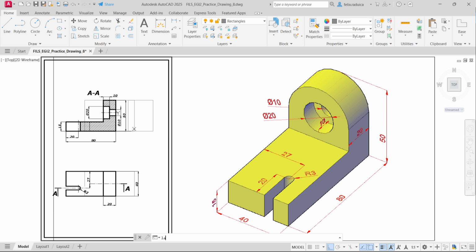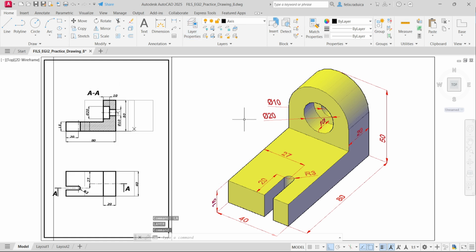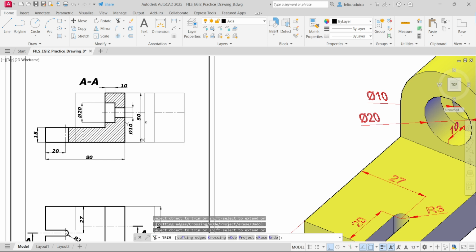So let's begin by switching to the axis layer. And we have one axis for, actually this axis here will go like that. So we can say line enter, click on this one and make it perpendicular to this, and then trim it here and delete the excess from here like that.